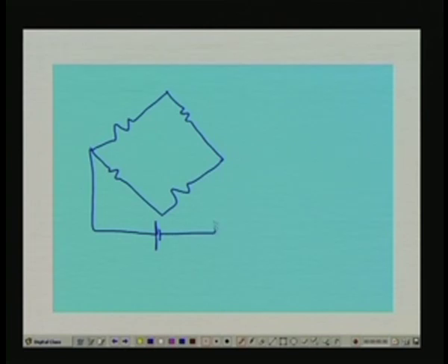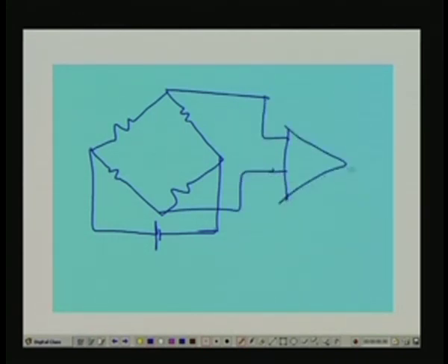So we have the cold junction compensation circuit. These circuits will be used along with the thermocouple circuit in a final signal conditioning circuit, so as to avoid any change in the ambient temperature.